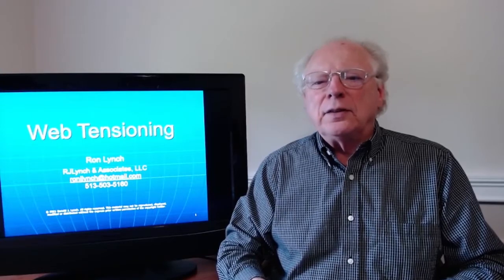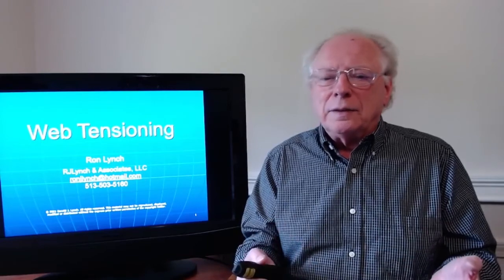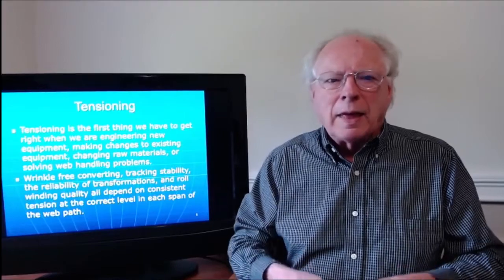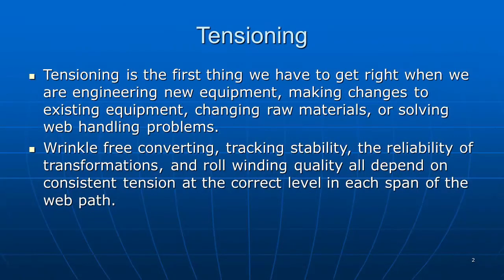This presentation is about web tensioning, the placement of driven rollers and idlers in a web path, selecting the right tension for the web, and how to select the velocity for the driven rollers. Tensioning is the first thing you have to get right when you are engineering a new web path, engineering the equipment, making changes to an existing web path, changing raw materials, or solving a web handling problem. Wrinkle-free converting, tracking stability, the reliability of transformations, roll winding quality, all depend on consistent tension at the correct level in each span of the path.